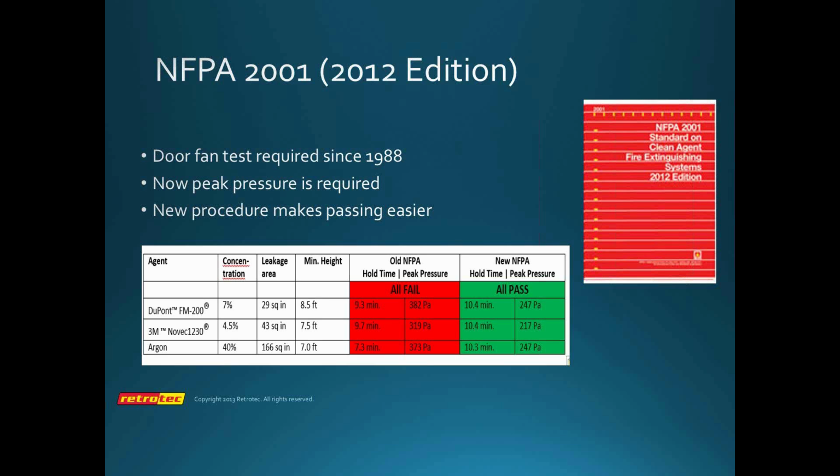So that does benefit us to some degree, particularly with inerts in North America, because it means that we have to put less effort into making the enclosure tight, and we're less likely to have to install pressure relief vents where they're not needed. And at this point, we actually know when they are needed. In this particular example that I've created here, neither of these enclosures need a pressure relief vent.